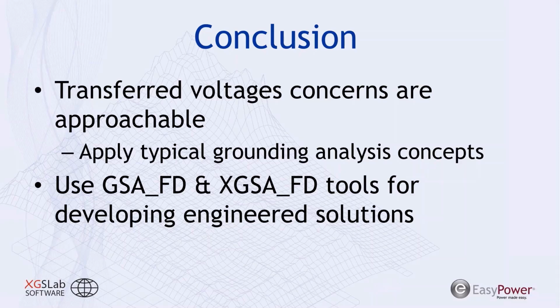Personally, I think the best methodology is that the standard should indicate that touch voltages and transfer voltages should meet the criteria from IEEE 80, which accounts for the differences in those voltages between the soil and the recipient, the clearing time that is associated with that, how long somebody will have to withstand that shock, and what the human body's threshold is for that shock. So that would really be the more holistic approach in order to analyze that. Good question.